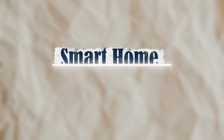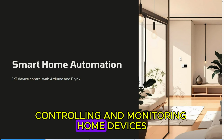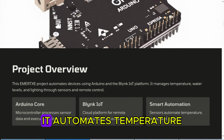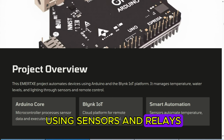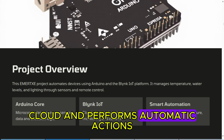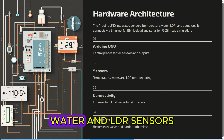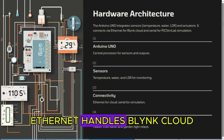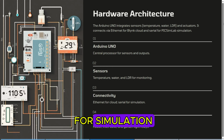Smart home automation. My project is called Smart Home Automation, controlling and monitoring home devices using Arduino and the Blynk app. Project overview. It automates temperature, water level, and lighting using sensors and relays. The Arduino reads data, sends it to Blynk Cloud, and performs automatic actions. Hardware architecture. The setup includes temperature, water, and LDR sensors connected to the Arduino. Ethernet handles Blynk Cloud communication, and Serial connects to PICSimLab for simulation.